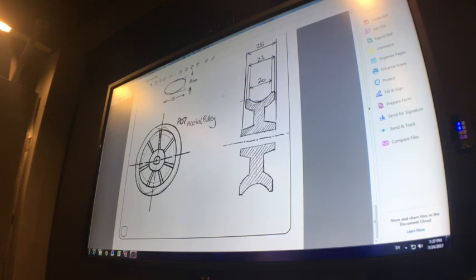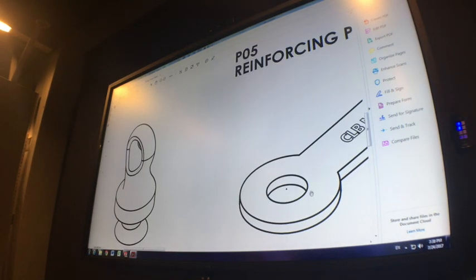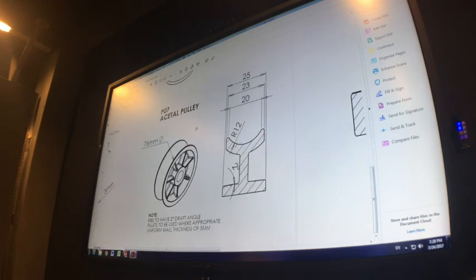The information we're given on this first one, with this section view, shows us that the wheel is going to be created using a revolve, much like we've done on the start of the pin at the bottom and on the washer to begin with. Like the washer, this one has a hole going through the middle. So the first thing we are going to do is sketch this profile, get all that dimension fully defined, and then revolve the wheel. After that, we will add the internal detail,